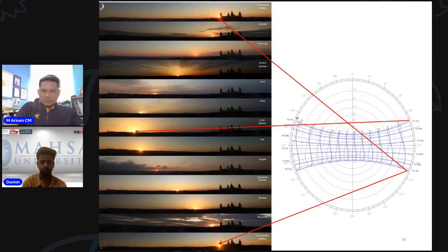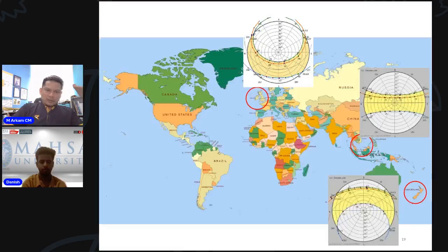In our climate, basically we can have flat or slightly slanting to the south, much better, because the coverage to the south is greater than the coverage to the north. This is coverage to the north, from the equator to the north, and from the equator to the south is more space for us. So that is why we set our solar panels at 20 to 25 degrees facing south, because the position of the sun is more precise there in terms of where we do our research. So that is how the positioning of the sun works.